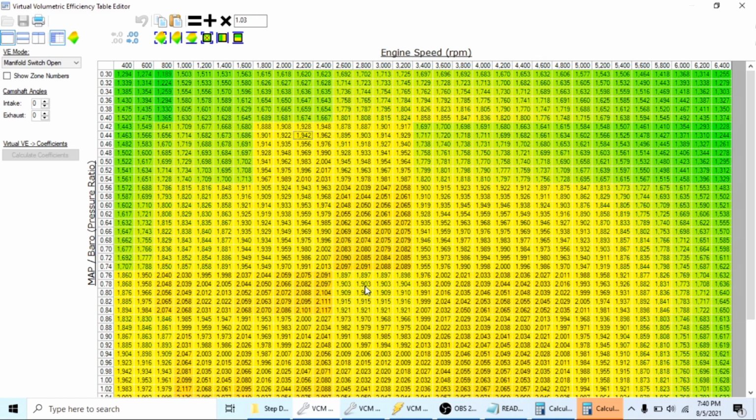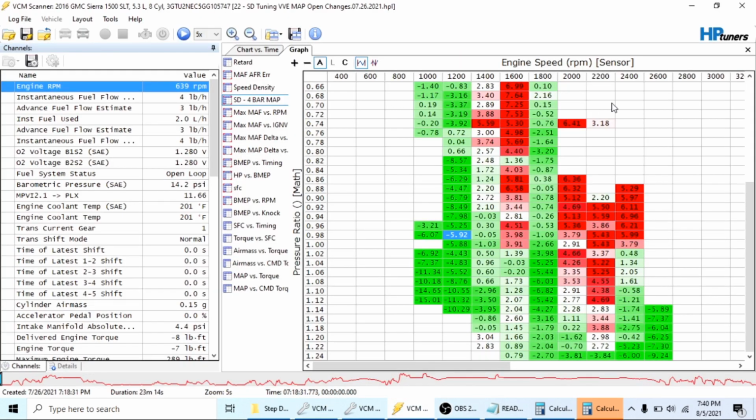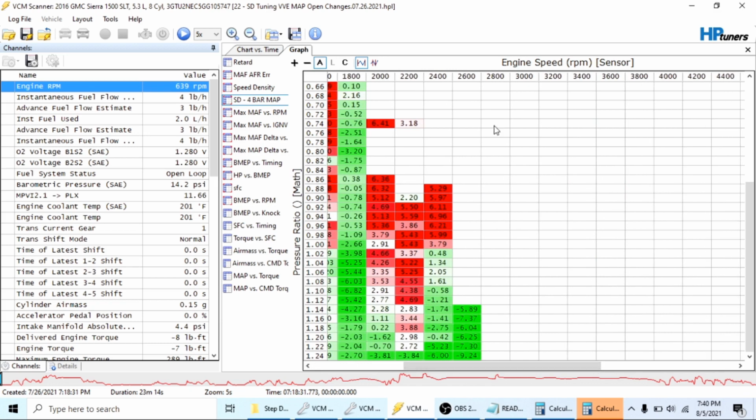And through each one of those operating conditions, taking logs down, looking at my logs, and just seeing where my data is lying. Let's say I'm at the highway speeds now, and I'm starting to fill up more of the higher RPMs, and I maybe got data from 2,000 up to 3,200. Then I look at the data and ask, is there a specific area that's much richer than another area, or a certain area that's much leaner, or are they all pretty rich, or all pretty lean, and just attack it from a holistic perspective versus just grabbing all of these.